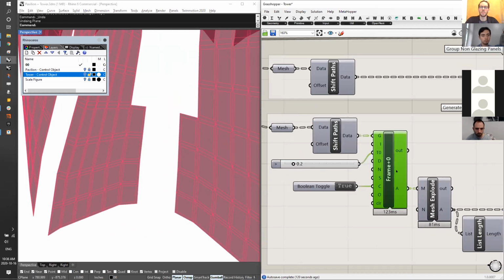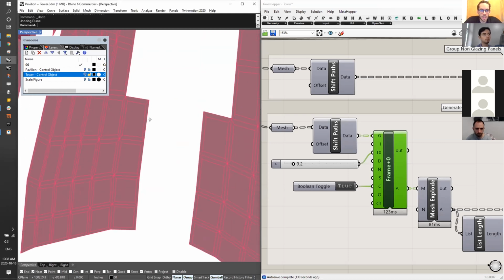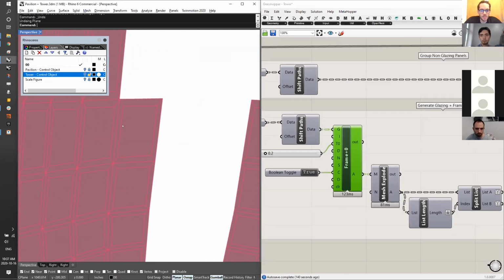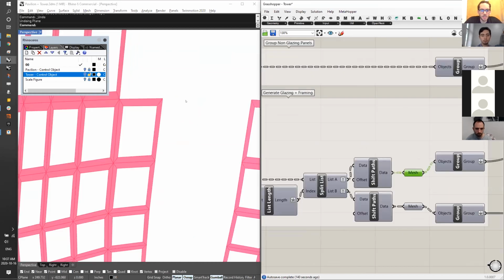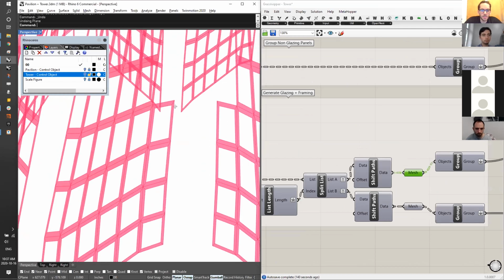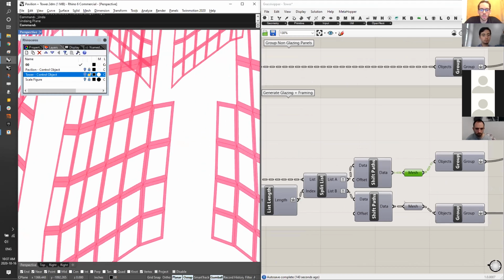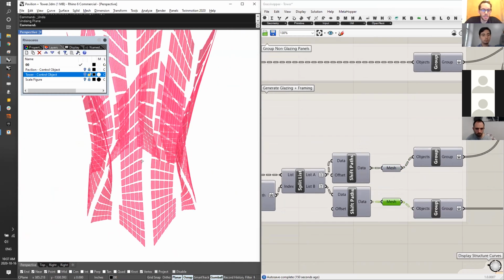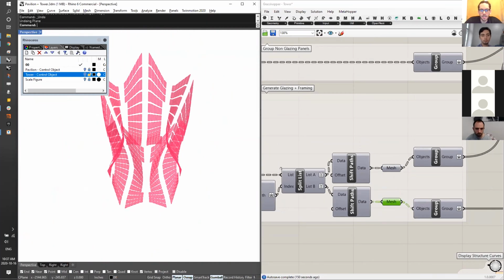There's a particular component called Frame+, and it's in the Mesh+ component library that David Mans wrote. And essentially all this is doing is creating a frame around inside the face, and then within the face it's creating another face. It's a simple little script that does a lot of good work. But for our purposes here, for the sake of creating the overall, you can create the framing of the windows, sort of the mullion so to speak. And then we can create the actual glazing elements, which are any particular framing object inside that.